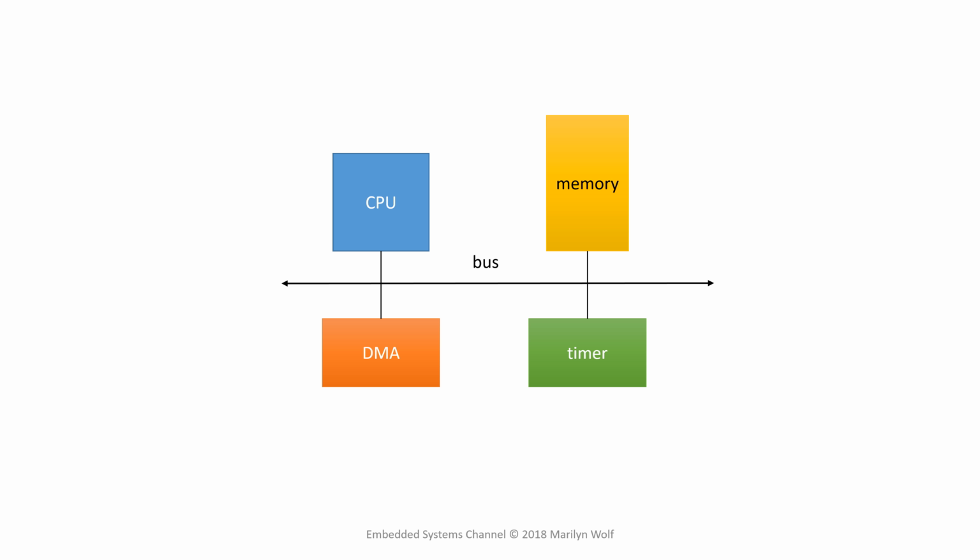Once again, here's our generic computing system. Direct memory access, or DMA, is an important mechanism that we see in both small and large systems. Direct memory access is a specialized device that performs transfers on the bus without executing a program. DMA access is more efficient, faster than programmed transfers on the bus. DMA uses two signals in a 4-cycle handshake. It uses a bus request signal to ask the CPU for bus mastership.